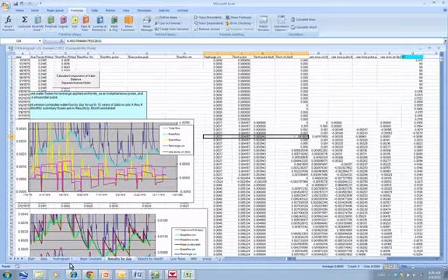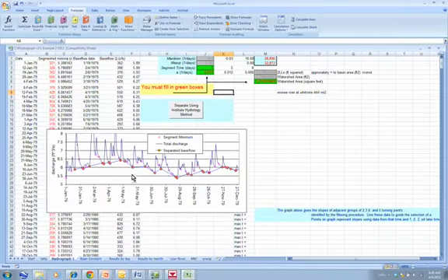So back here, when we're doing this analysis, we say there's base flow here, and there's base flow here. And then between these points, we have to make some assumptions about what's going on. The simplest assumption is that there's recharge that is uniformly distributed across this interval.